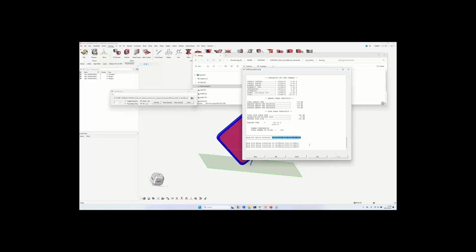Yeah, really interesting question. And the second one from Marius is, OpenRadioss is running locally on the personal computer, right? Is there unlimited usage of cores? There's no limitation, of course. So you can run it on MPI, on a larger cluster, whatever you have. You can use Intel MPI or Open MPI and run it on a very huge cluster, as well as on your local machine, like I'm demoing it here live.